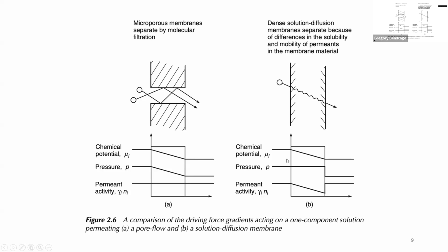So in that case, for a pervaporation membrane, which is used for separating, say you want to make non-alcoholic wine. So you have to get the alcohol out of the wine. So you put the wine over here. You have a membrane that allows alcohol through, but not water. And then the alcohol condenses over here, and then you evaporate it. That's a pervaporation technique to make, if you wondered how they made non-alcoholic wine.